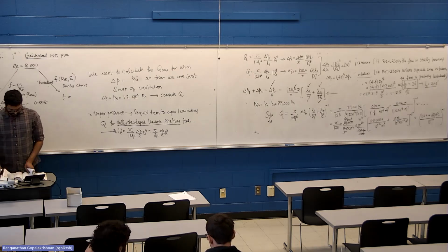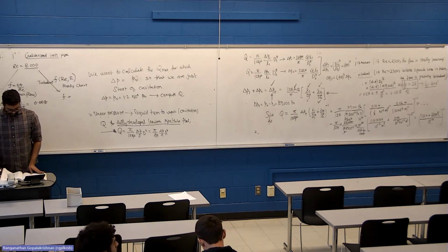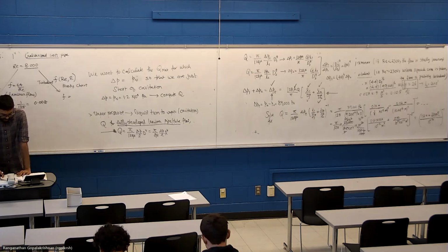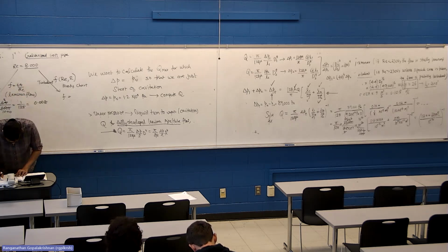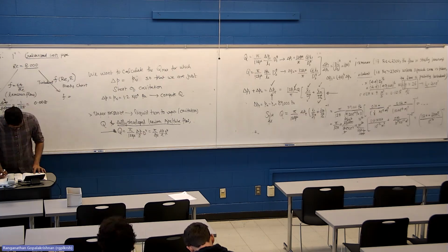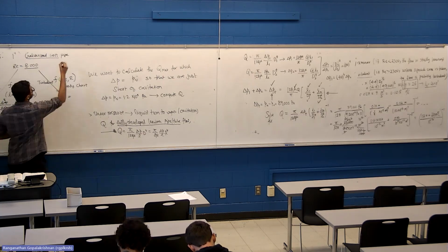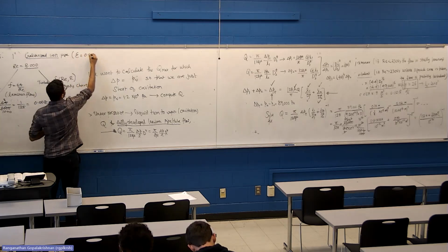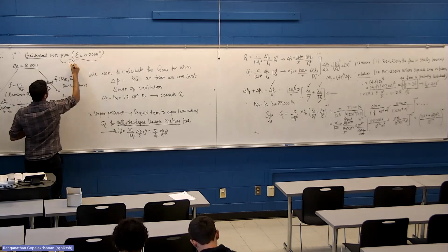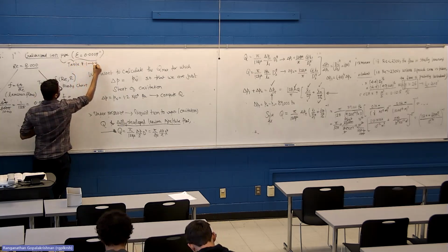So switch over to page 431, which will be provided during the exam. Use that Moody chart to calculate the friction factor at Reynolds number of 8,000. And for galvanized iron, the roughness epsilon is 0.0005 feet. This is from table 8.1, also will be given.